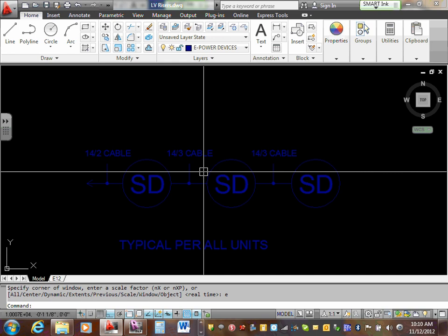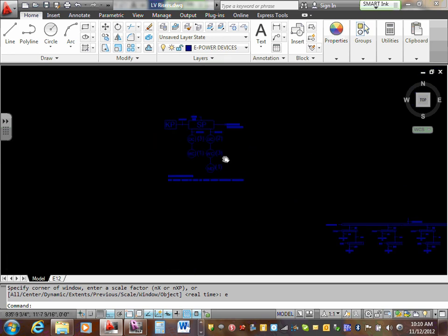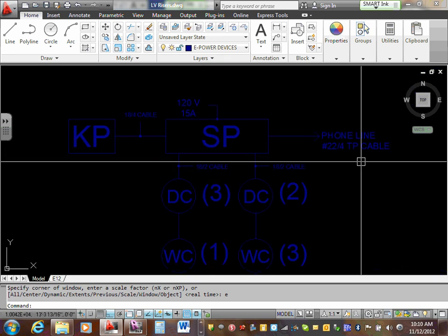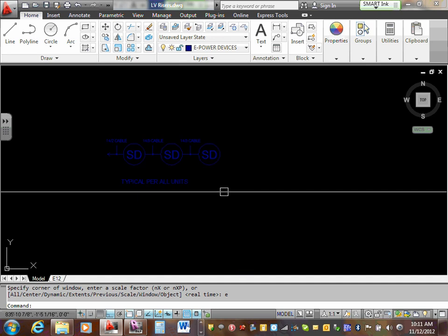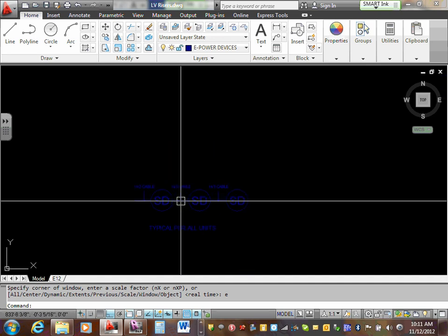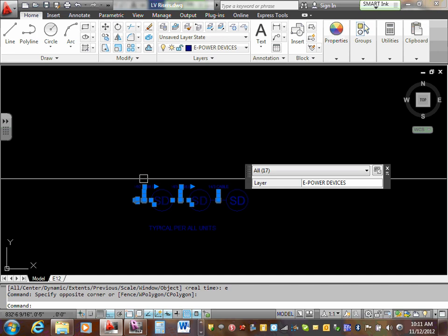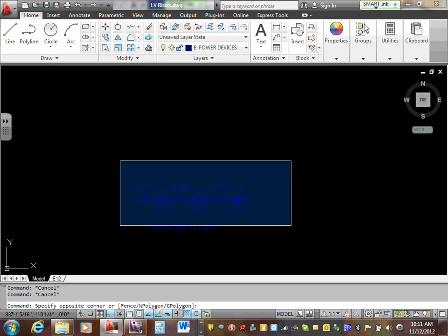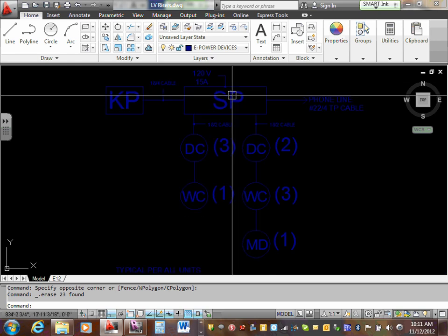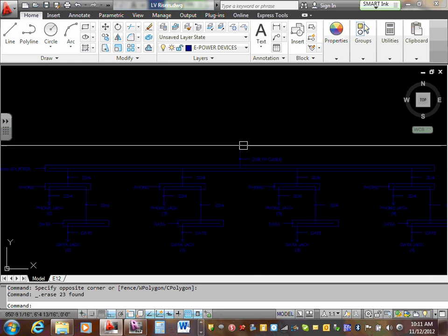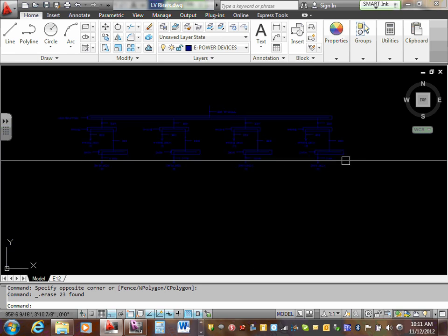The other one, guys, that you want to do is the fire alarm. The fire alarm panel, it's going to look exactly like this. It's going to be a fire alarm control panel, annunciator panel, and all input-output devices the same. Can I have thumbs up that we understand how fire alarm is going to look like in this case? Do you guys remember the one that we said fire alarm right here? That one, the smoke detector, that's really not true here for the commercial building. So that one here, I'm going to delete that one. It's going to be typical fire alarm. It looks like security panel. Okay. Low voltage riser. Remember how we get the phones and the data?